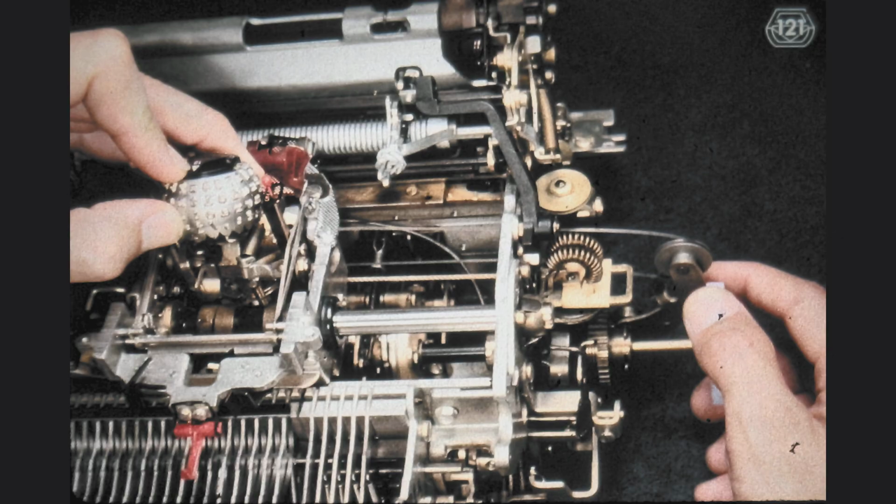While we attempt to install the rotate tape, we must be very careful not to act on the detent cam follower or the detent actuator arm, because inadvertently releasing the rotate detent will allow the spring to discharge all of its tension very quickly, with a very good chance of breaking off a tooth of the element.